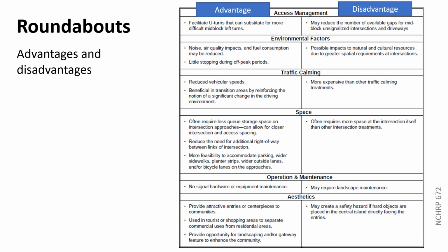Traffic calming, really, we use mini roundabouts, which is a whole different class, for traffic calming, right? A standard modern roundabout on, let's say, a state highway isn't really a traffic calming device. They will reduce speeds through the intersection, but in general, we use them for, number one, safety, and number two, usually efficiency. We're keeping traffic moving through there.